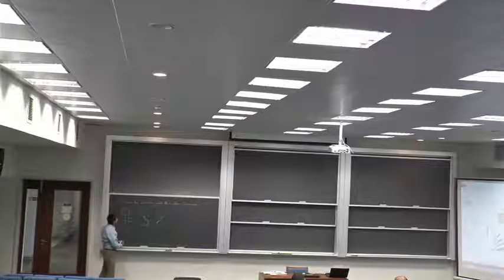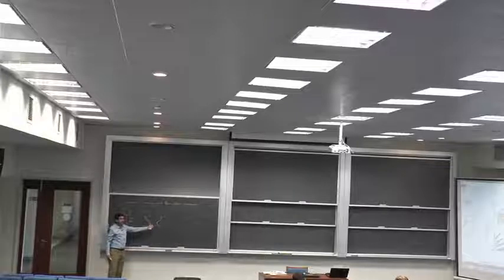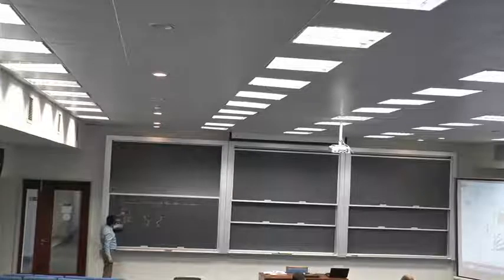Now you can argue that if I actually place this mass symmetrically and I control the environment in such a fashion that there are no air currents and this mass is perfectly symmetrically placed on top of a perfectly machined Euler strut, then would such a scenario arise? Yes, the scenario would arise even if we perfectly balance this mass on top of the strut and everything is symmetrical.